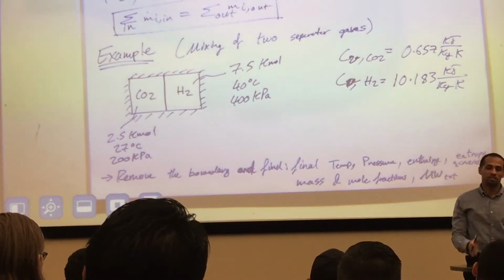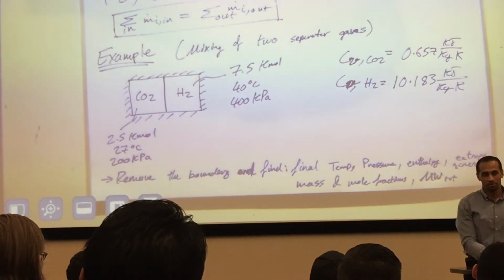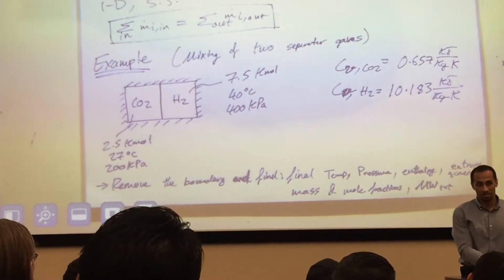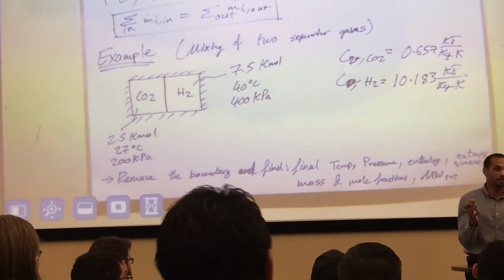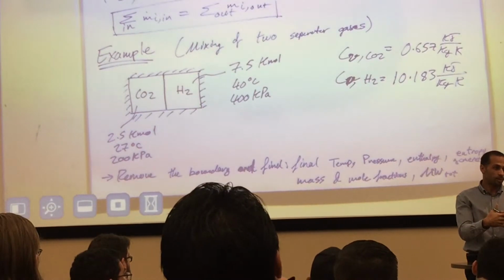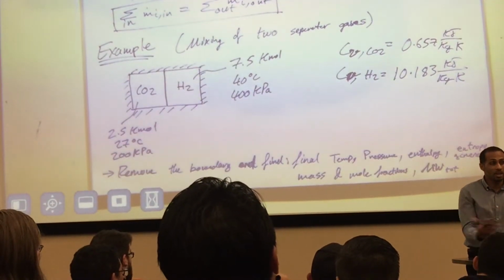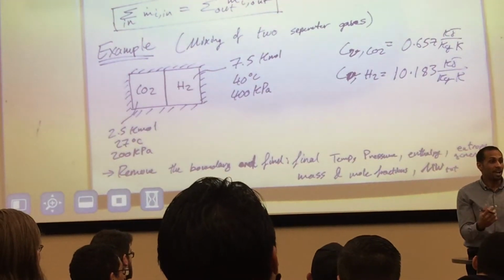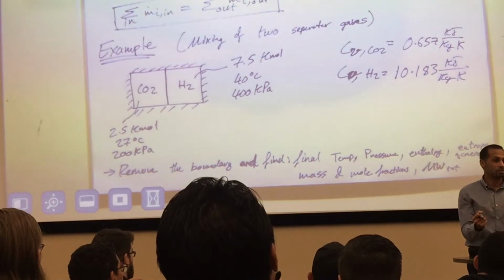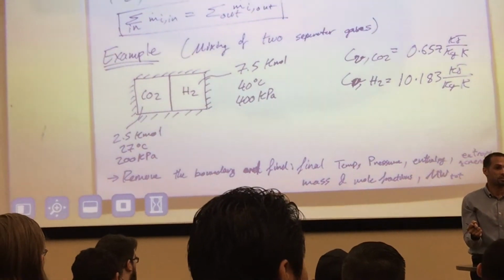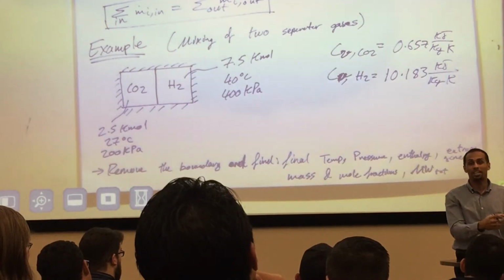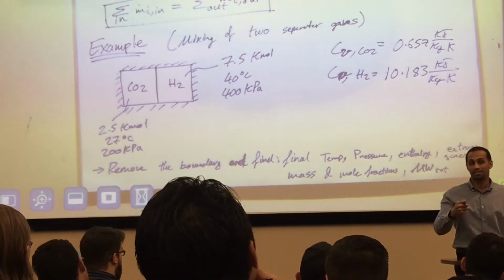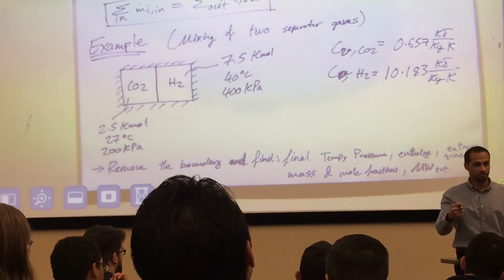So what your colleague mentioned is if I have two gases at the same temperature, same pressure, I just remove that barrier all of a sudden and they diffuse together, right? They're not going to react. I'm not going to get energy. But I do have entropy generation. What is that entropy represented in? That entropy is the amount of energy that it will take me to separate those gases again.